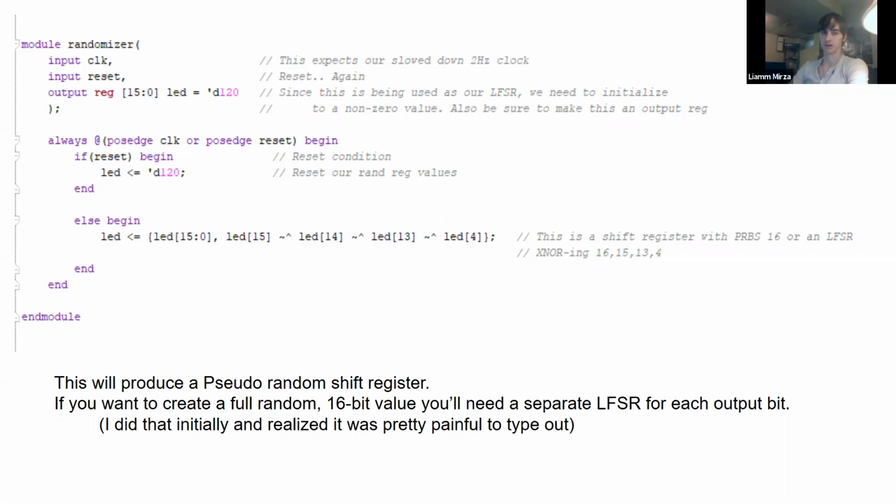Did it state how large the sequence was in that document you found? Well, it'll be 15 bits. But there's also a feedback. The way it works with PRBSs is it's the max value of it. Like PRBS 7 is 127, 2 to the n minus 1. That's how you calculate how many unique values you'll get before you repeat. Then it'll just loop back over again. So in this case, we have 2 to the 15 minus 1, which is a lot of different sequences.